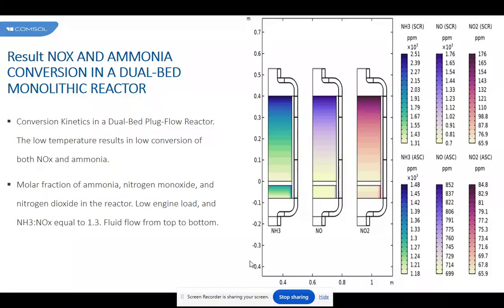In view of the literature extant on the subject of the effect of fluid distribution and cell density on the light-off performance and recent commercial developments, this simulation presents a computational study of the effects of using dual cell density structures in monolith catalytic converters. The effects of such structures on the velocity and temperature distributions and subsequently on the chemical conversion is demonstrated for a variety of dual cell configurations. The computational model. This section describes the computational model implemented. A description of the domain.